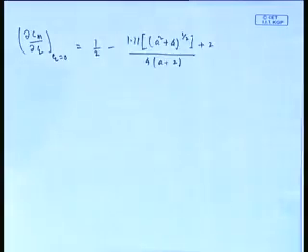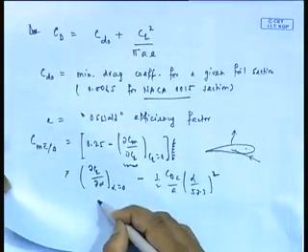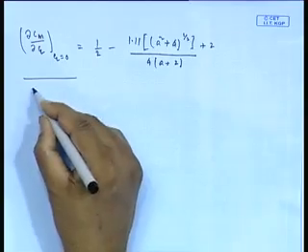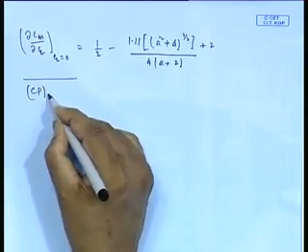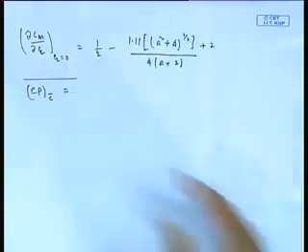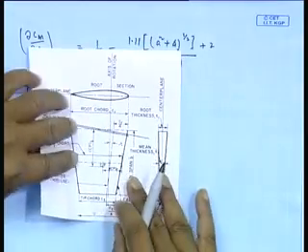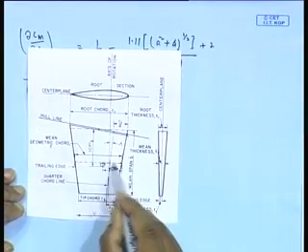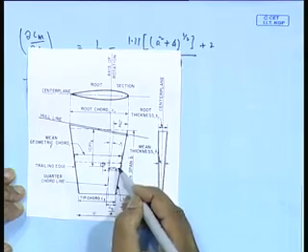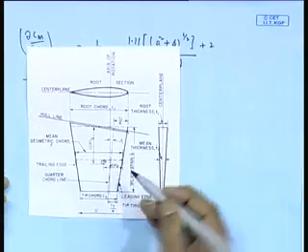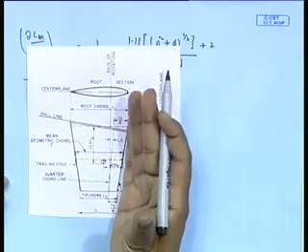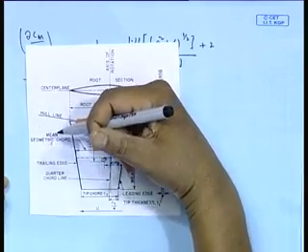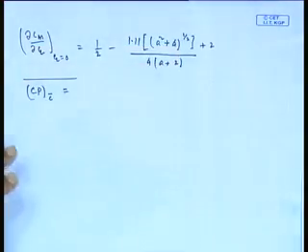And of course, dCl by d alpha we have given already. This term is of course given in the earlier formula. And now center of pressure, Cp, C bar. Remember, C bar is chordwise, that is what we mentioned here. This distance is measured from here, the leading edge. You are basically measuring in two coordinate systems. You measure the x coordinate from the leading edge, the front edge, and the z coordinate, or y if you call it, from the top side, that is the root side.